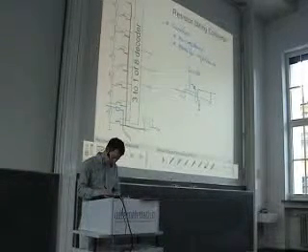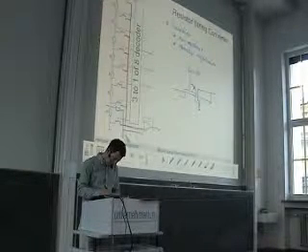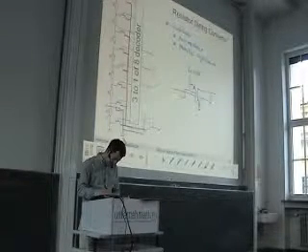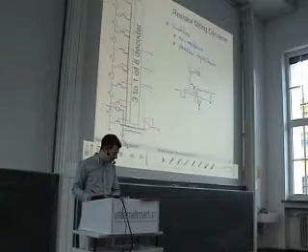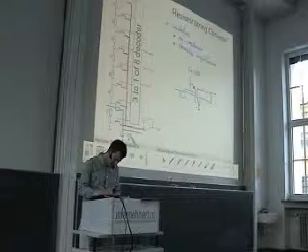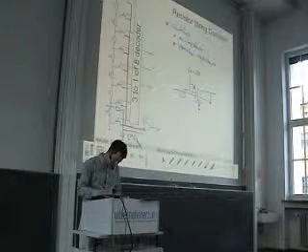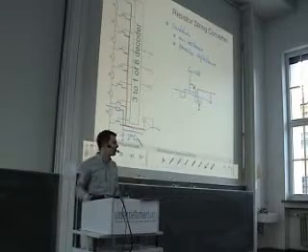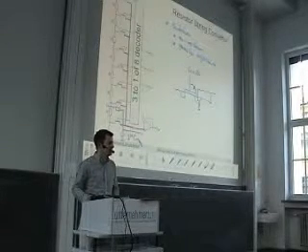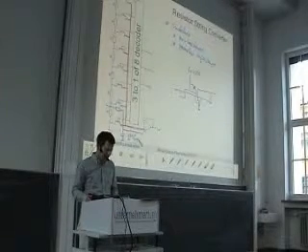Then, before we go to the op amp, we have here a parasitic capacitance as the sum of all transistor caps. So we have here 2 to the power of n times a parasitic capacitance, let's call it CT, C transistor. And important is that we have 2 to the power of n of these guys.